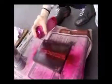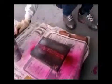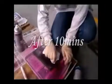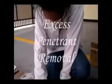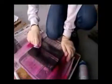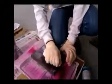The penetrant is usually a brilliantly colored mobile fluid with very low surface tension and high capillary action. The penetrant is allowed dwell time to soak into any flaws, generally 5 to 30 minutes. The dwell time mainly depends upon the penetrant. The excess penetrant is then removed from the surface. The removal method is controlled by the type of penetrant used.